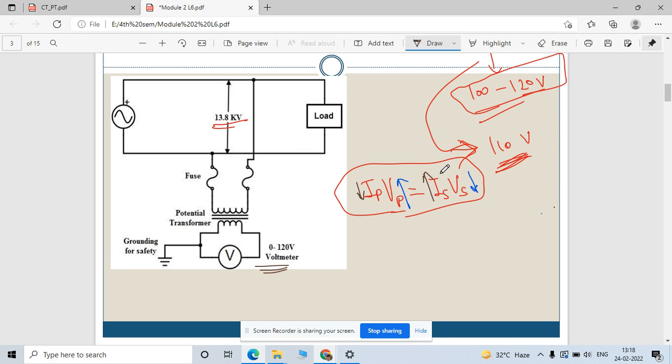So for that, you need to see here that the overall resistance of the secondary winding is very small. But in the voltmeter case, as I also explained regarding the functioning of a voltmeter, the internal resistance is very high, so a small amount of current flows through it.